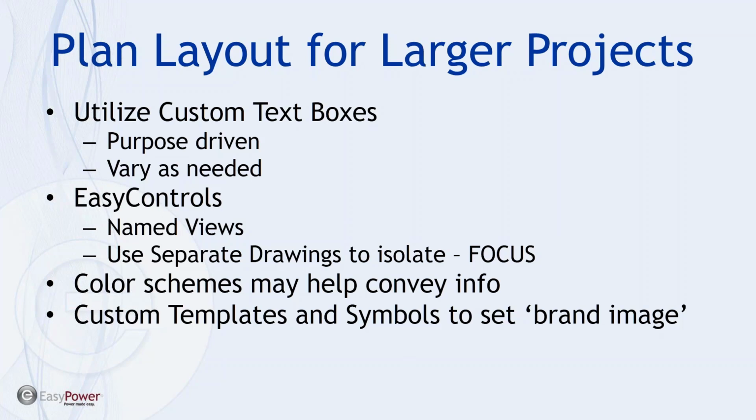I might want to display different data as I'm doing the layout or drawing the OneLine, as opposed to what's going to be presented when I print the OneLines out for my client, or I print them out for my maintenance team to do data collection or other maintenance on a specific piece of equipment. Most of the information we're going to be talking about, specifically custom text boxes, are a feature of EasyPower 10.0.